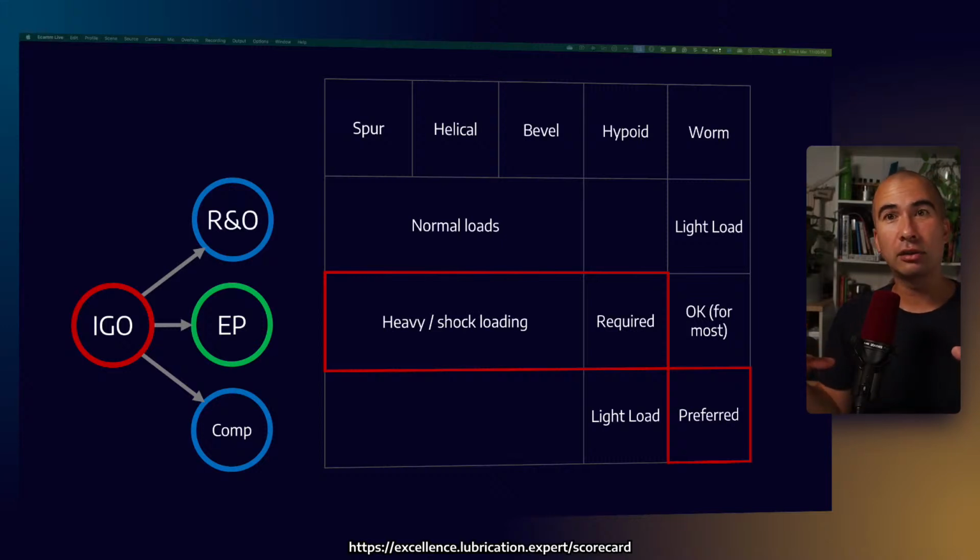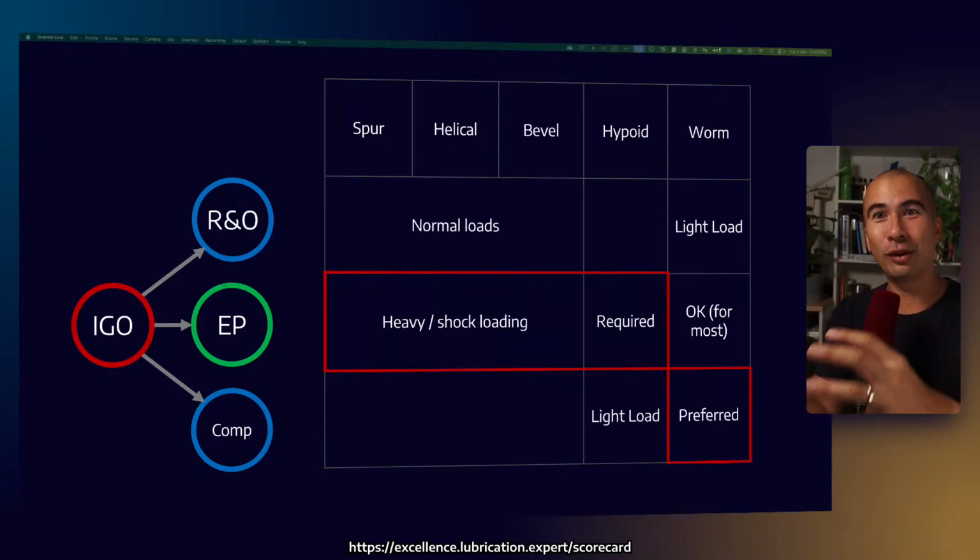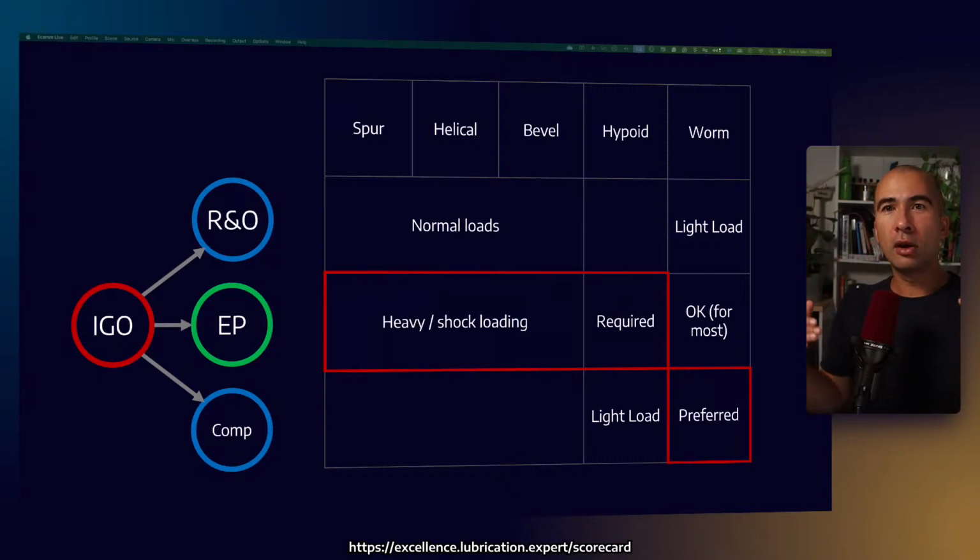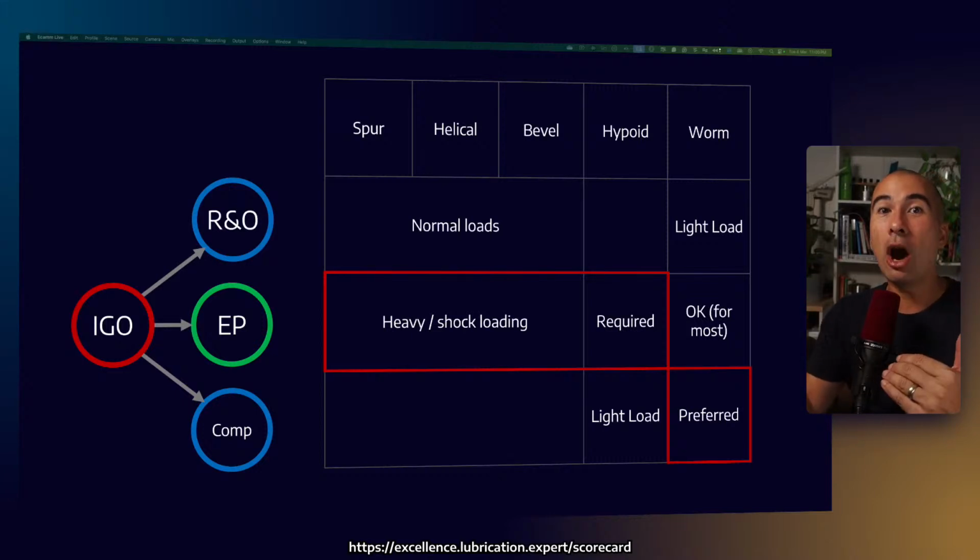Now, there is actually a class of lubricants called supertractor, STUOs, supertractor universal oils, which can not only lubricate all of those components, but also function as the engine oil as well, right? And remember, when we asked which oils are the most highly additized, the most highly additized oils tend to be the engine oils, because they contain not only the R&O, they contain the anti-wear, and they also contain detergents. So generally, an engine oil will be over-engineered for something like a hydraulic oil application or even for some gears, right? That's why in some cases, you can get away with an engine oil in a gearbox.